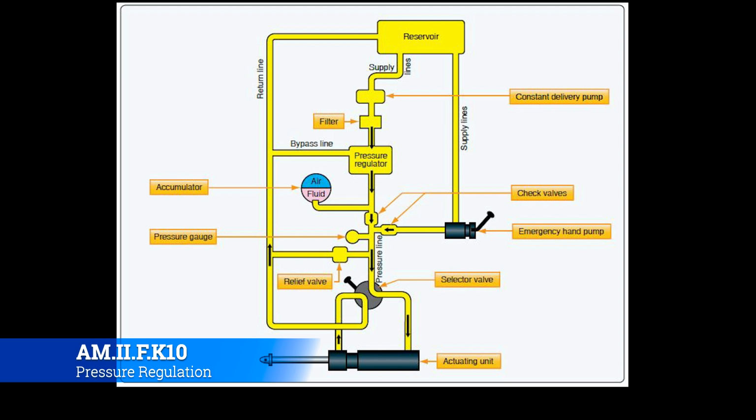Now, the relief valve and the pressure regulator are basically similar in a lot of different ways. The regulator's purpose, though, is to regulate the pressure at a certain psi. The relief valve, however, doesn't have that regulatory function, but mechanically it's going to work much the same way. It's going to have a certain hydraulic pressure setting where if it gets anywhere above this, the valve will open and allow pressure out of the system to keep it from basically turning into a big pressure bomb. The mechanics between the relief valve and the regulator work the same way.